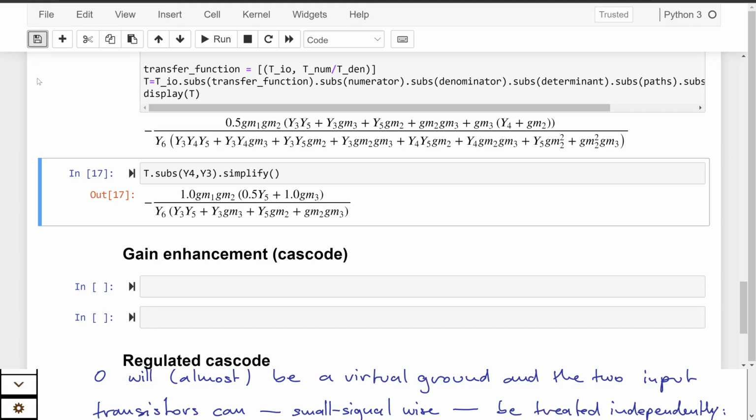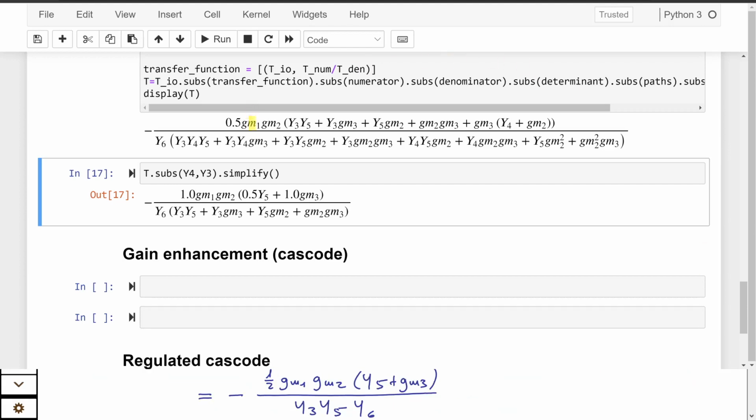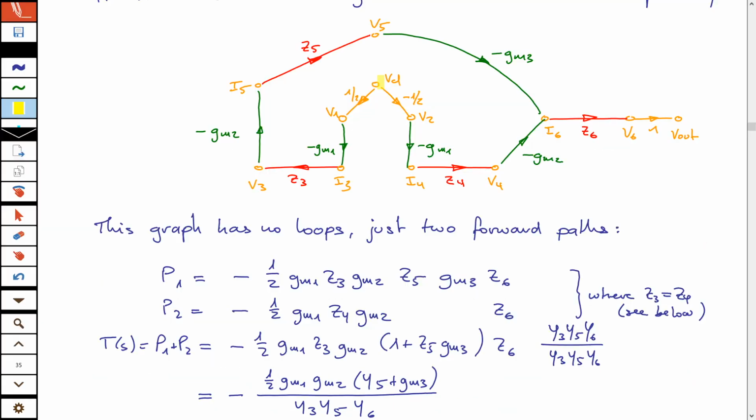Any of the paths through this system cannot have transmission zeros. If you look at the signal flow graph I have drawn here, the only thing you have is one forward path going this way, and this forward path just has poles, doesn't it? And I have another forward path, and this forward path also just has poles. And the only thing that could cause any zeros is that one path has this and the other path doesn't.